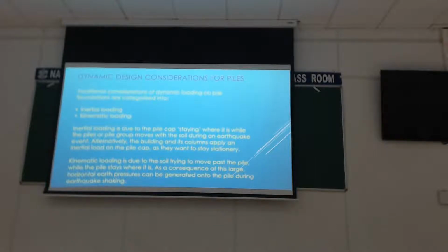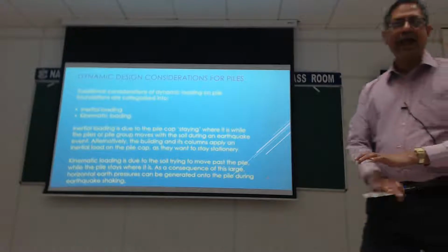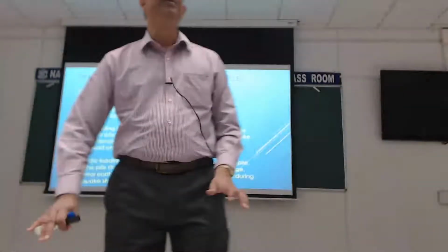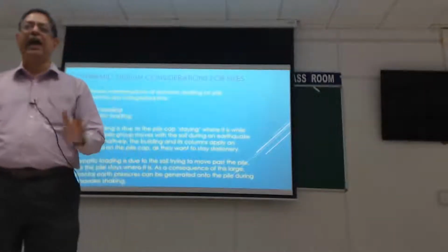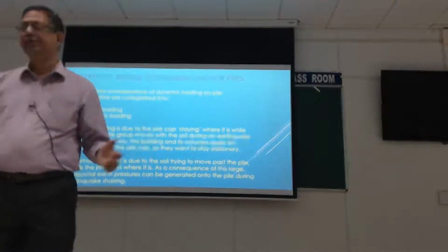But these two have been known for ages now as the significant loads you've got to design your piles for. Because these are horizontal loads, they will induce a consequent shear force and bending moment. And you need to design the piles to carry this extra bending moment. Otherwise, you will get broken piles. And this is without any complication of liquefaction or anything. This is just piles going into ground and oscillating.